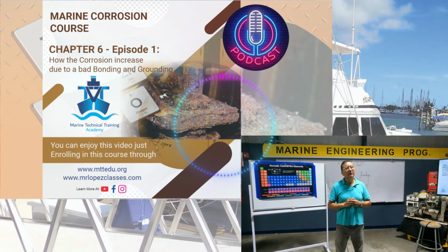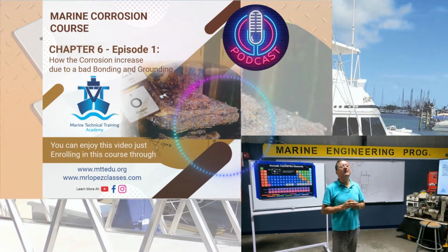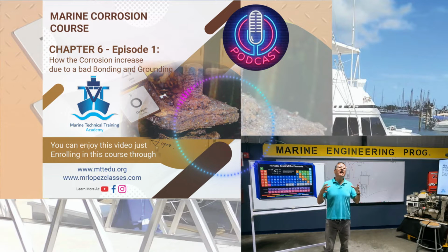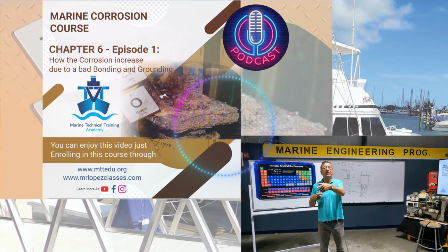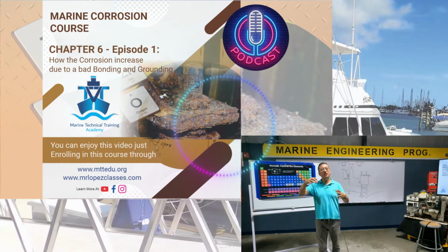Fuel tanks, if the fuel tanks are metallic, aluminum or stainless steel. Blocks of the engines, block of the generators, through holes, metallic through holes, cabinets. All the metallic parts inside of the boat shall be connected to the bonding conductor. Oh, if the metallic element is located above the waterline, it's not necessary to connect it? Yes, all the metallic elements inside of the boat should be connected to the bonding conductor.